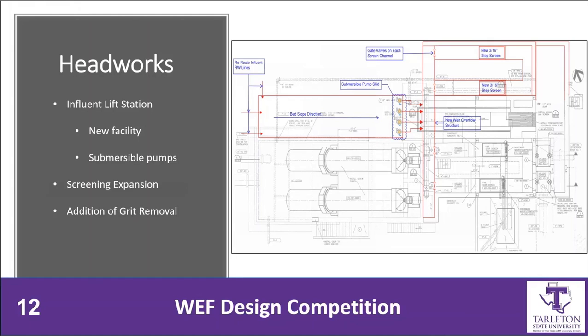The capacity of the screening facility will be doubled by adding 2 screens of similar specification to the existing, constructed such that the entire facility will share an influent channel separated from each screen channel by gate valves to give the operators complete control over the flow. During our site visit, we learned that the plant experiences a great deal of sediment buildup that plant staff have to manually shovel out on a regular basis.